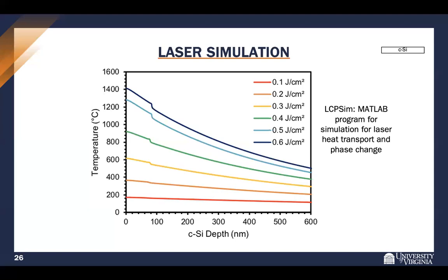It is a bit idealized. Another issue is it has difficulty taking very small steps. I can set it to small, 10 nanometer steps, but based on how it works, it will automatically increase the step width. I didn't write this code. It does have the change in refractive index and extinction coefficient with temperature for silicon, for pretty much all temperatures up to the ablation temperature. So it calculates the temperature stepwise, evaluates if the pulse is still there, how much is reflected, how much is absorbed, and then recalculates how much the temperature increases. From there, it calculates how the heat diffuses.